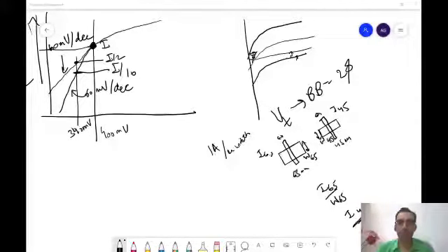Yes, sir. So when you say that we see the amount of current flowing through the device, do you mean from source to drain or vice versa? Because when we measure current before the cutoff, before VT, the leakage current happens through body and source or body or drain. So do we have a fixed standard of current flowing through the device?